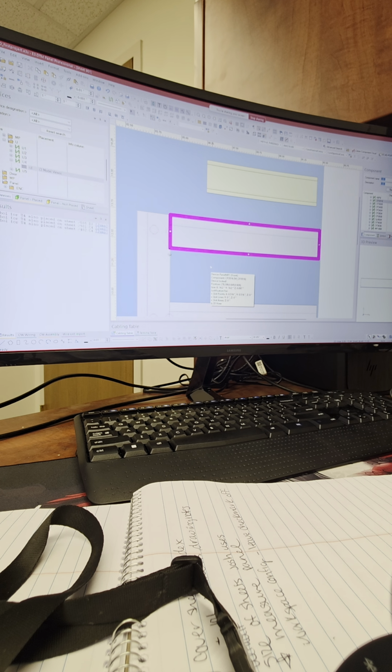Right click on U4 in the device tree structure. Say unlock. Yeah, unlock object, top third one. Yeah, I think there was an accidental selection. Okay. Yeah, we just accidentally locked this U4. That's why it was showing gray in your device tree structure.